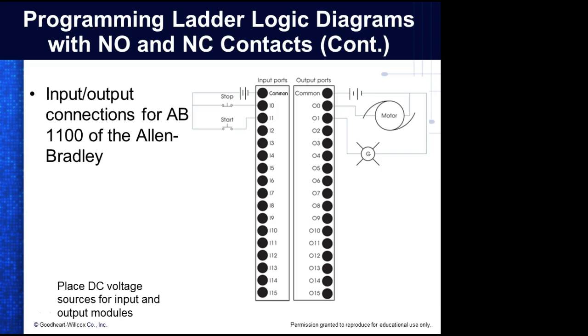So when we put our PLC in monitor mode, you flip a switch and the screen won't change colors for about 2 seconds, and then it'll change color. So you're trying to run a counter and you're sitting there waiting on it to change. You're waiting on your counter to update and it's not updating because it is updating, but it's updating in the CPU. It just takes so long to send that back to your computer.